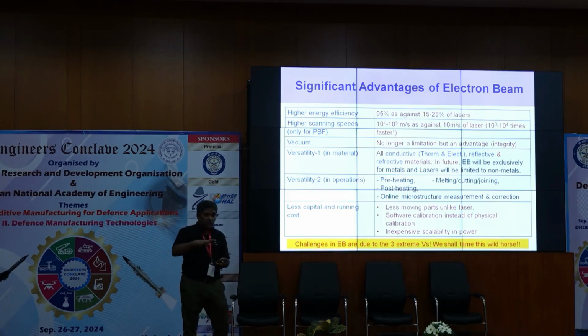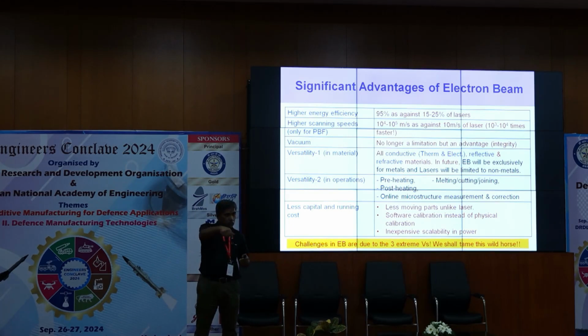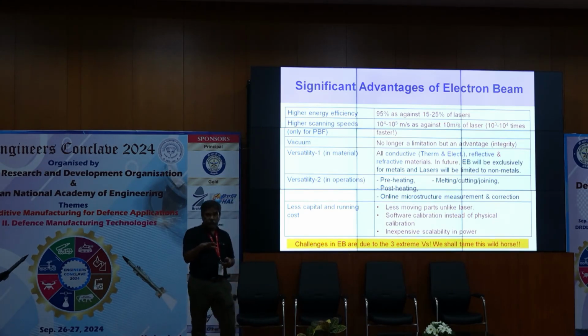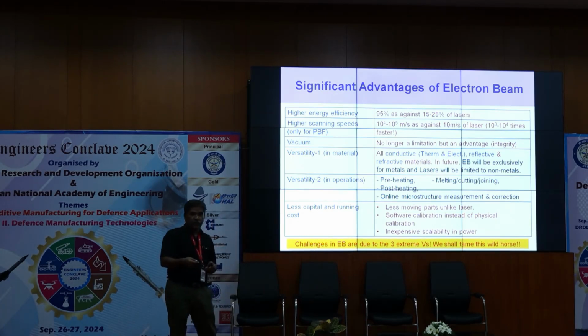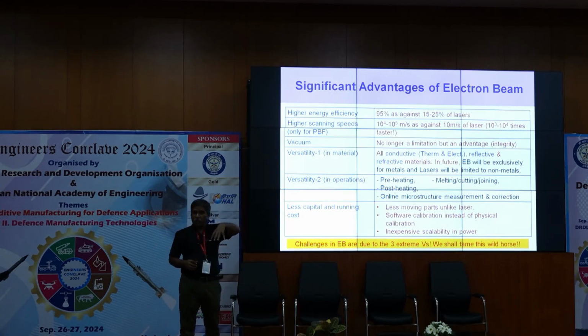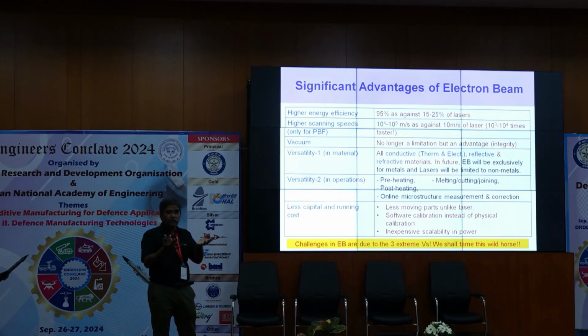So imagine that you have a powder bed, you want to scan a circular area by several rasters and a circular loop. That movement will take place at 10,000 meters per second. That means each layer you can scan in milliseconds. But then you don't get enough temperature. But the entire circular area is uniformly rising in temperature every time. Every time it is 0.1 degree centigrade, 0.2 degree centigrade. So you keep on doing the scan, repeat the scan till you cross the sintering temperature. So instead of doing one single scan and put the bed into inhomogeneous temperature, it's more like flashes in the camera. Every time it's a flash, therefore the temperature rises very uniform.